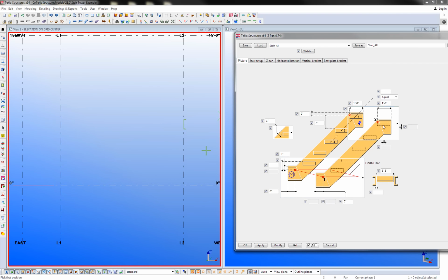You can see that the base stair, if I wanted to do the bottom and top of the stringers manually, my nosing points are located point 1, point 2. Those are the two places I pick. If I were to change this to where I want to land on a beam, you can see that my picking order has changed. It's now nosing, nosing, landing beam.